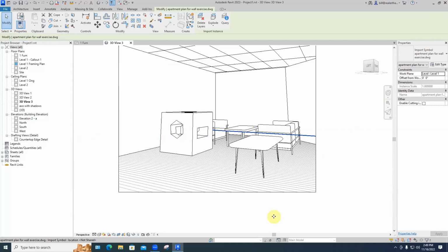I want it to be 24 inches high, 8 inches at the base from the edge to the center line, 12 inches at the top from the outside to the center line, but the center line doesn't actually touch. We're going to sort of leave that hole the way we did in the demonstration on Monday. So the edge of the hole will be a ½ inch off the center line. And for this, we're going to get into not the plan view to start with of the Family editor, but into, let's say, the front elevation view.